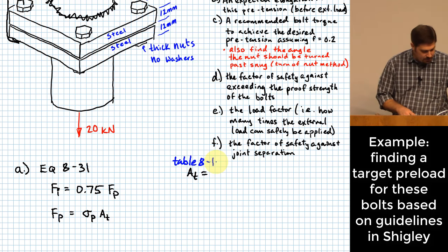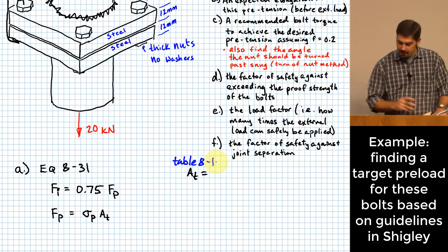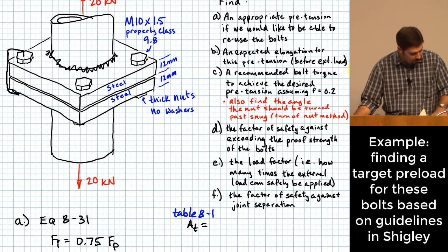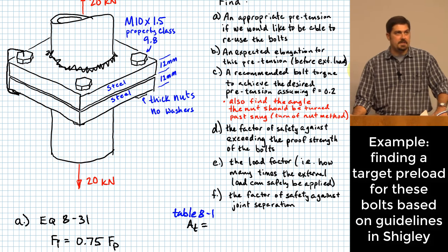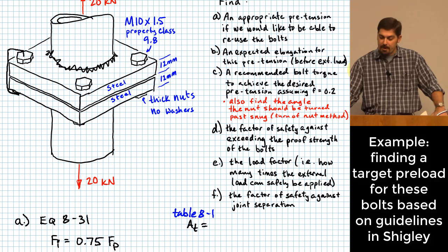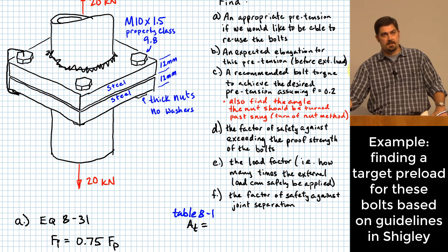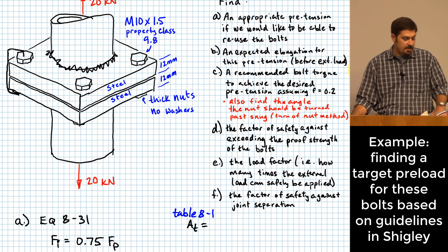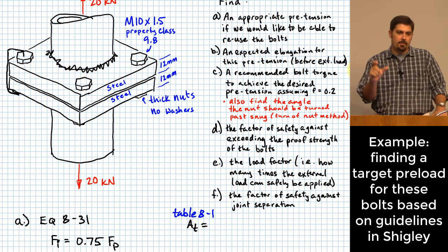Then we actually have to look and make sure we're in the right pitch series. Okay, that's what the second number represents there for an M10 by 1.5. You'll notice that in the left column you have 1.5 pitch. So this gives me a chance to mention that how you specify a number of threads per unit of length is different in the metric system than it is in the US system. So what we've done so far with our previous problems is we have done a measurement that is in threads per inch, right? In other words, a number of threads per unit of length.